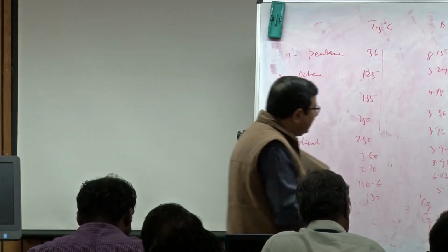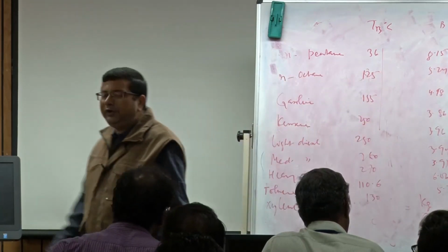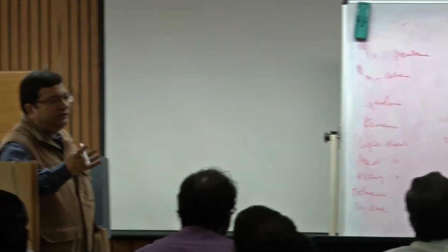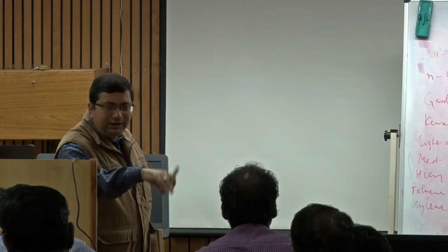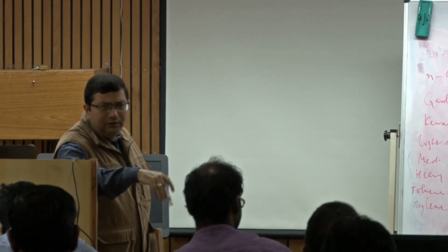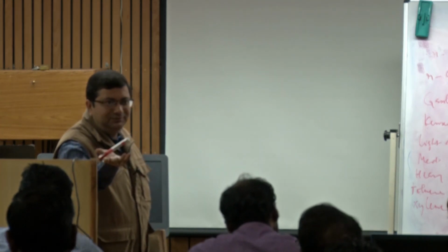And another thing, since we are seeing that B is not varying much, it essentially becomes a function of droplet size. B depends on the fuel property. So, if there is no much dependence on that, we do not have to test it with the real fuel. We can test it with water, right.